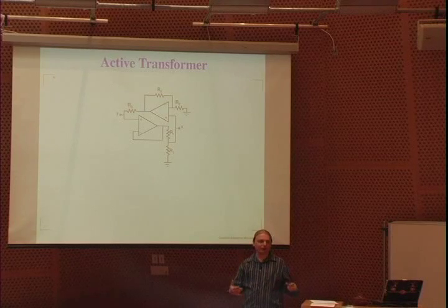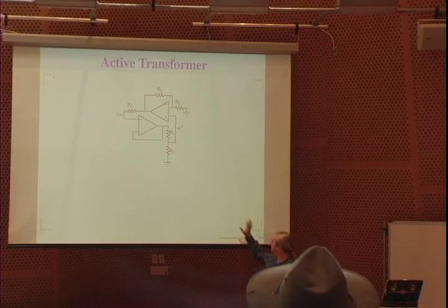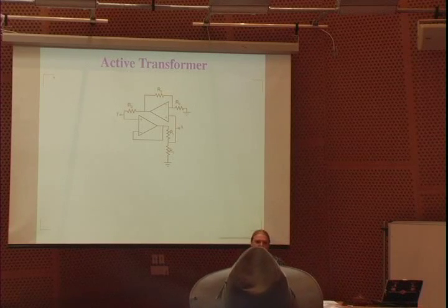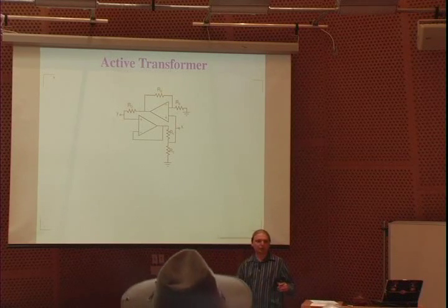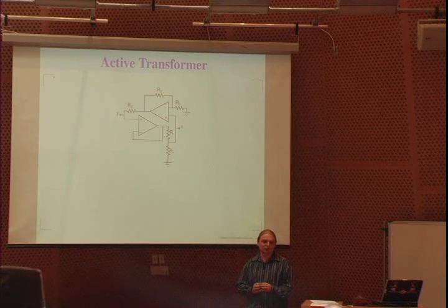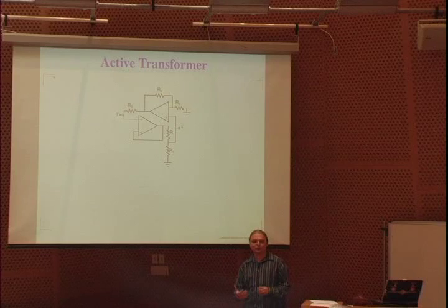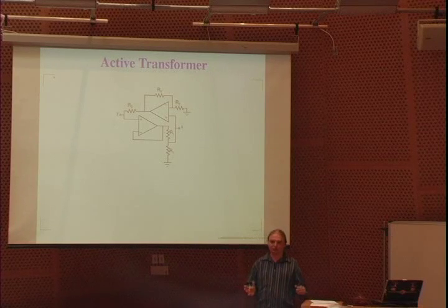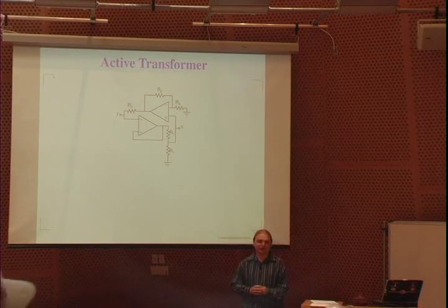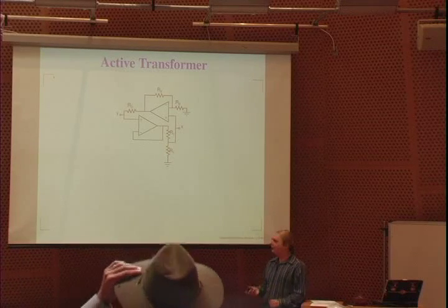the voltage on one side will, in this case, be twice the voltage on the other side. But I can always take something like this, drive it with something stronger, hold both voltages to be equal, and then I need to output reasonable currents. So to solve those problems, I needed to make a sort of generalized active transformer. People have built active transformers before. This is yet another way to do it.